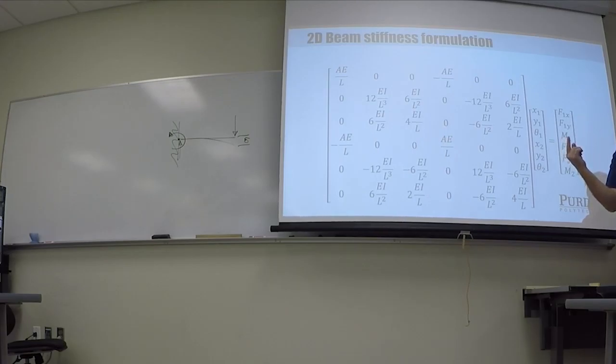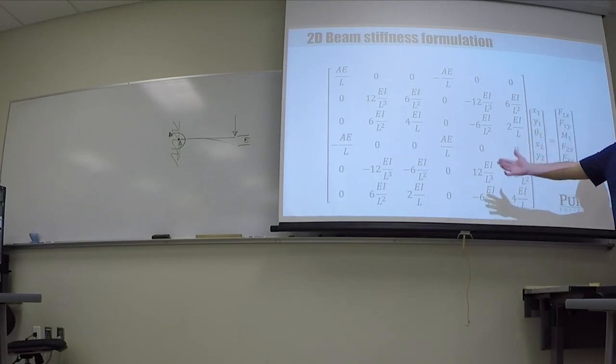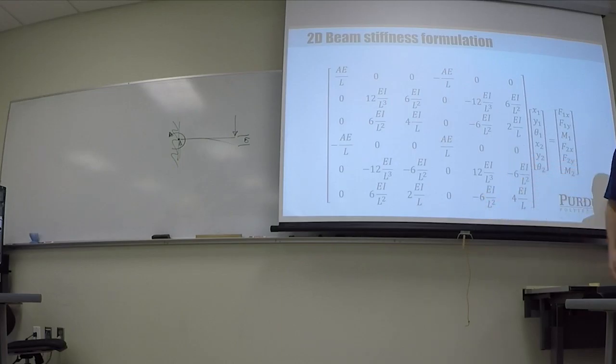So how many elements are in the Kennedy bridge? Every single one of them has the stiffness matrix piled on top, and so you end up with a giant matrix that is tens of thousands or even millions by tens of thousands or millions. And that's why I said previously that this is not a realistic thing to do until you have computers to crunch all this math for you.